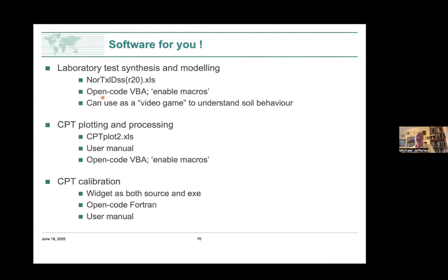CPT plotting and processing: CPT plot 2, if that's provided to you. This one actually has a user manual. I've taken you quickly through how to use it. Again, it's open code VBA, so you can look at the equations and the correlations used. Again, enable macros. The widget, I don't think I've actually given you that now. I'll have to provide that after we finish this talk. That is given both as a source file in Fortran 90 and as executables, and there is a user manual for that.